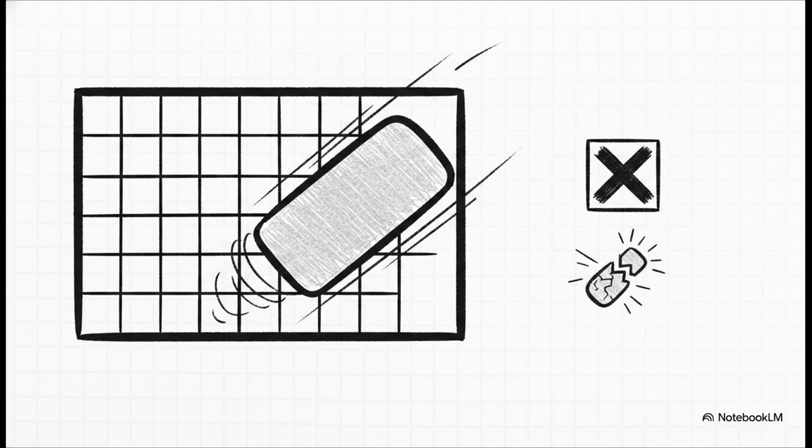First off, flash memory must be erased before it can be rewritten. If you try to skip that, the old and new values just kind of smush together logically into total garbage data. Second, and this is the real kicker here, you cannot erase a single byte of flash. No way. You have to erase an entire sector, or block, all at once. We're talking thousands of bytes wiped out entirely just to change a single bit. So yeah, you can see why our simple bit-by-bit SRAM test just won't work out of the box here.